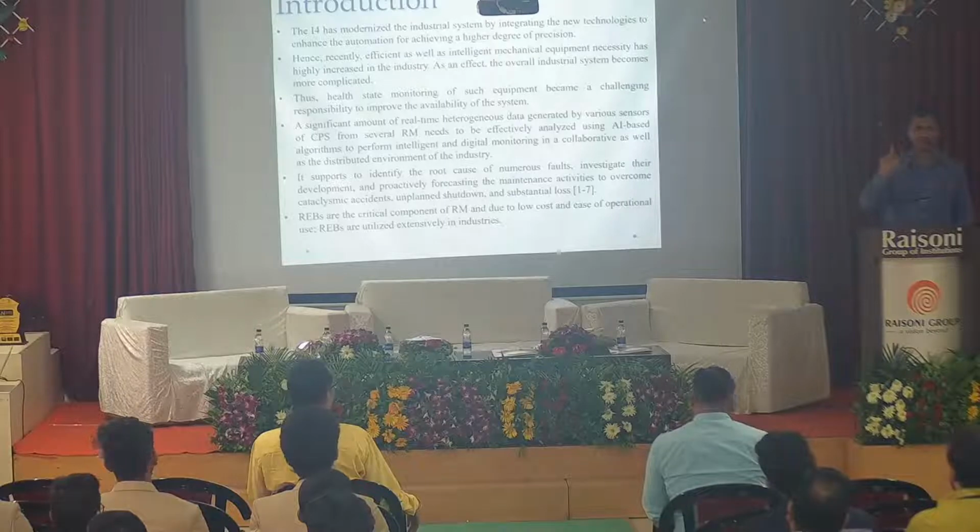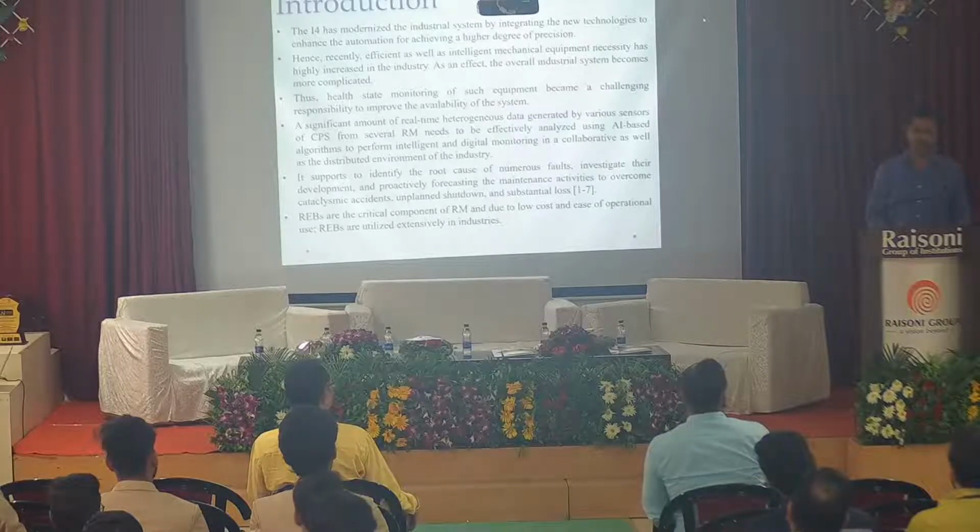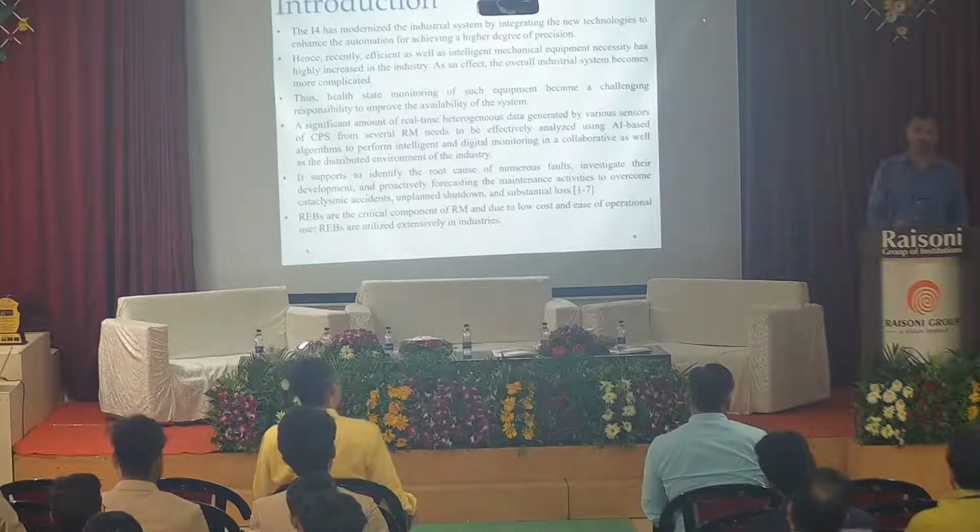When you come to know the bearing has failed, when you listen to the noise coming from the fan, it means the fault has already started a few days or a few months back. Only when your ears hear that do you come to know there's a bearing fault.